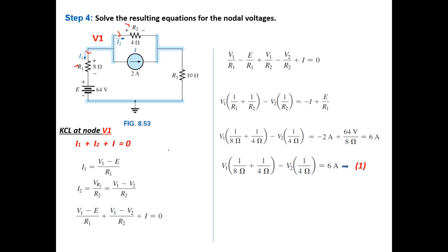So again, the Kirchhoff Current Law, we know it as what? That all the current entering should equal all the current leaving. So when I check these three here, I1 is leaving the node, so I will take it as I1 plus I2 is leaving the node, even so I2. Also the current source is leaving the node, so it will be plus I. So I will add them, and for this node I'm not having any currents entering the node, so equal to 0.